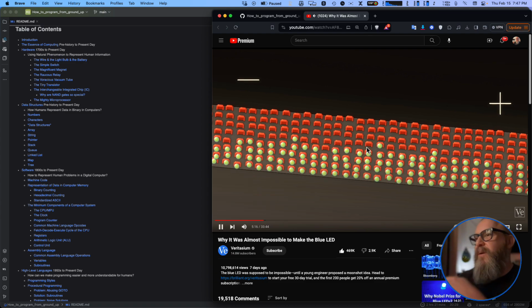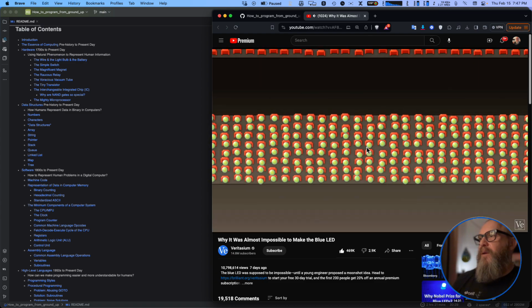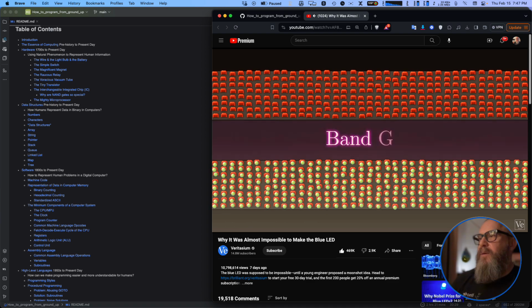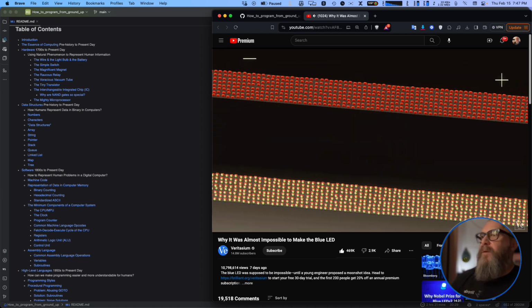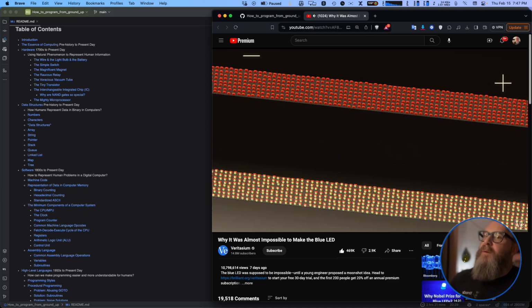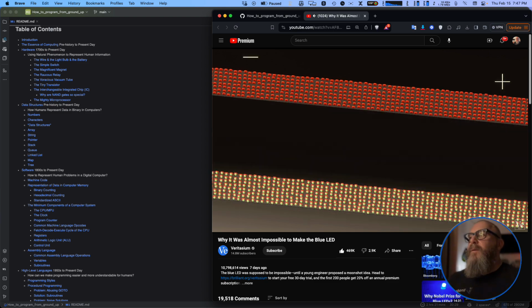In insulators, the valence band is full, and the difference in energy between the valence and conduction bands, the band gap, is large. So when an electric field is applied, no electrons can move. There are no available seats to move into in the valence band, and the band gap is too big for any electrons to jump into the conduction band.